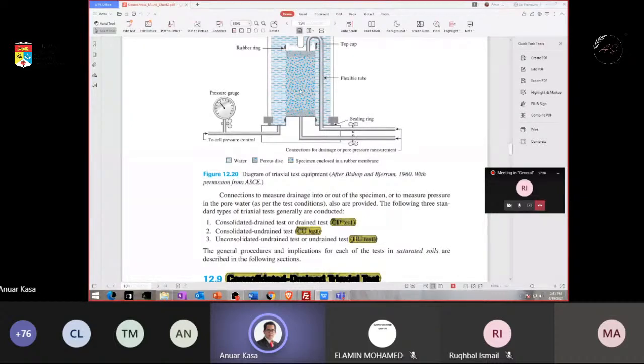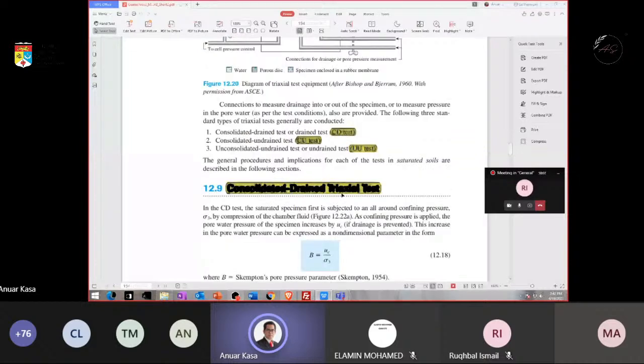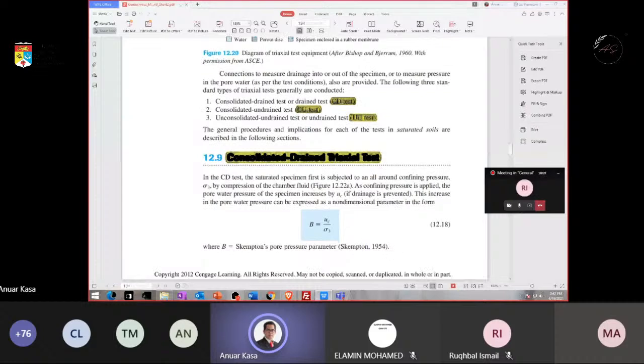So yeah, that is about the triaxial test. Actually, I already explained quite a lot in the video. I try to make it simple. The most important test for shear strength is direct shear, because mostly engineers outside ask for that result. And if the project is expensive, maybe they want to get a better design of the foundation, for example, then they request a triaxial test result. So they need to get the sample and run the test.